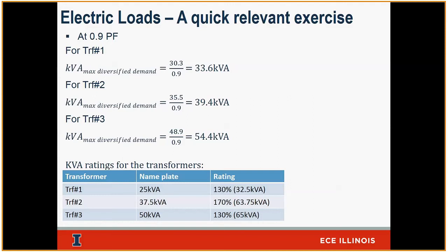Every time I am above that 130% loading value, I am actually taking away life from the transformer, depending on temperature and depending on how long I'm overloading it. I could actually calculate a loss of life percentage. So I can turn that into a year of life loss, a month of life loss, or a day of life loss on the transformer.